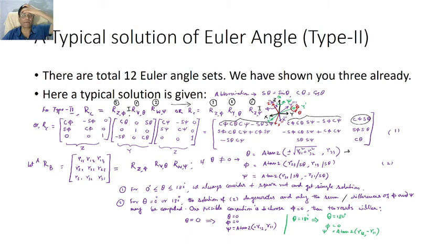And as you know, there are several sequences of operations which may lead to the same composite rotation matrix. This is one of them, this is another, and there could be others also. So we are trying to understand that here, since all the rotations are given with reference to some of the principal axis of the inertial coordinate frame only, you see z, y, z, the sequence is like this. So all have been pre-multiplied, and we deduced why earlier. So now let us see this operation. You can also see it this way, but here let us see they are the same.